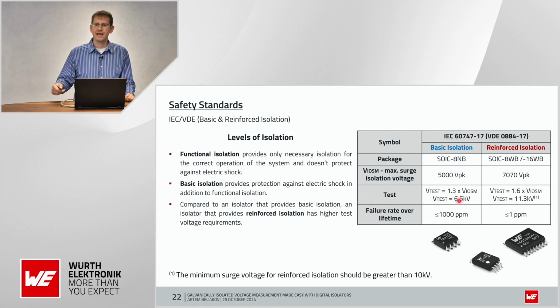And for basic isolation, the test voltage will be 6.5 kilovolt, and for reinforced isolation products, the test voltage will be 11.3 kilovolt. And according to IEC or VDE standard, the minimum surge voltage for reinforced isolation should be greater than 10 kilovolt.